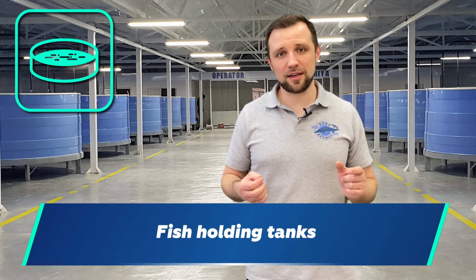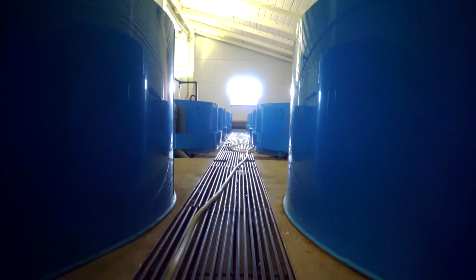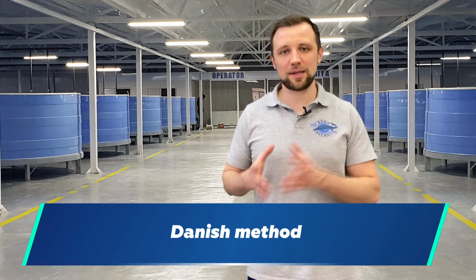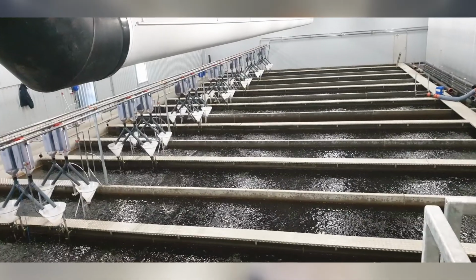Tanks. There are two basic approaches to the design of systems for trout farming. The first is conventionally classical, when we provide round tanks and a water treatment system and tie them together with pipelines. Well, in general, that's how basically all recirculating aquaculture systems are designed. And the second approach, let's call it the Danish one, because this approach originally came from Denmark. What does it mean? They make use of rectangular long canals and a water treatment system adjacent to these canals. The entire water circulation is virtually pressureless and with minimal variations. Often circulation is even provided only by means of air lifts rather than pumps.